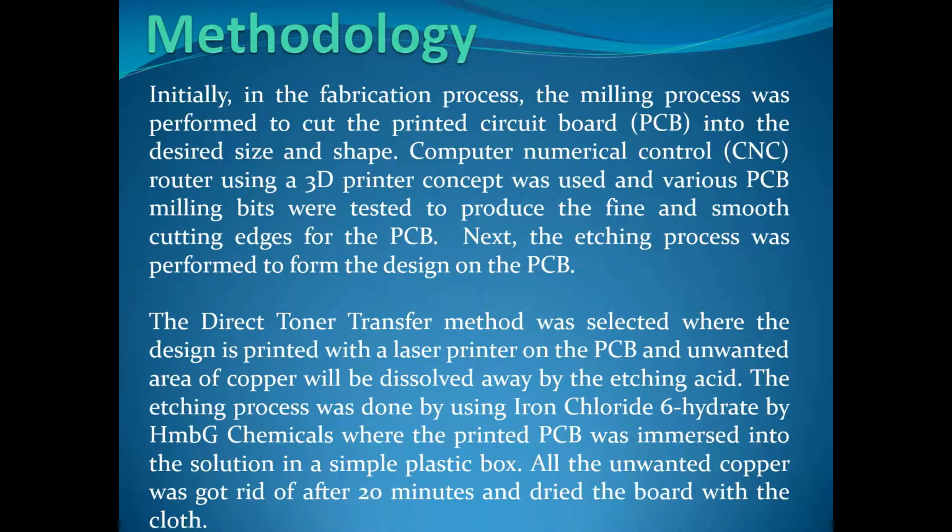Methodology. The fabrication process of the resonator. The milling process was performed to cut the printed circuit board, PCB, into the desired size and shape. A CNC using a 3D printer concept was used, and various PCB milling bits were tested to produce a fine and smooth cutting edge for the PCB.